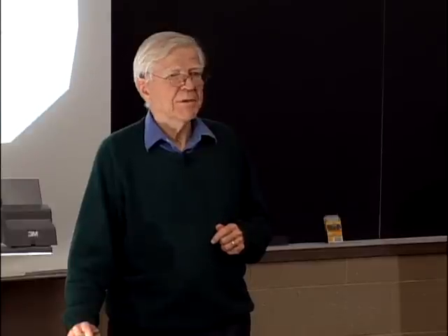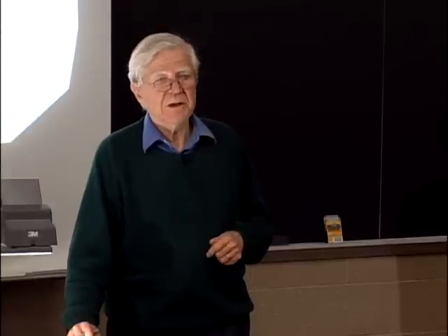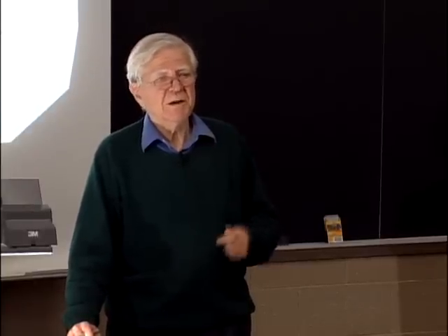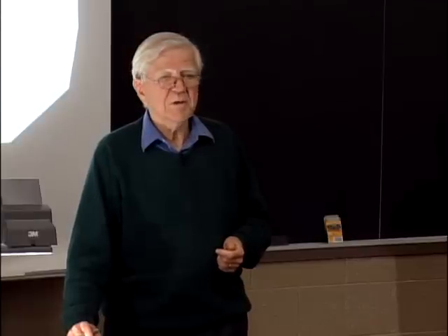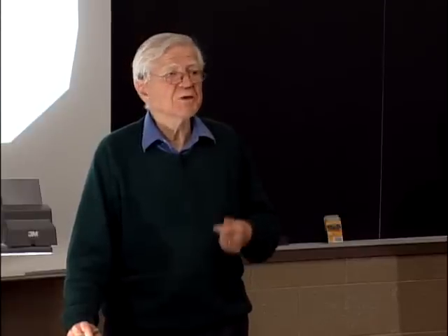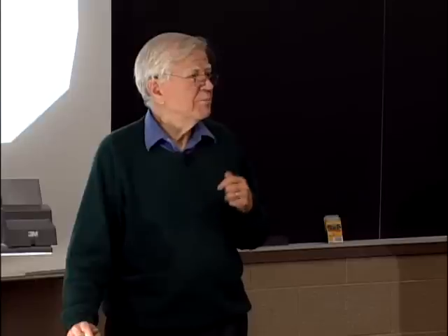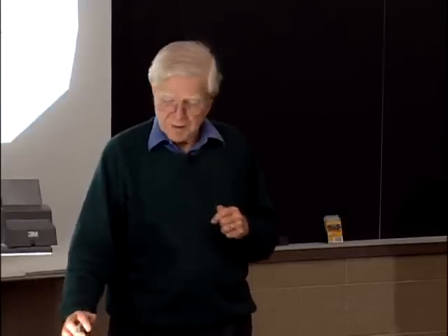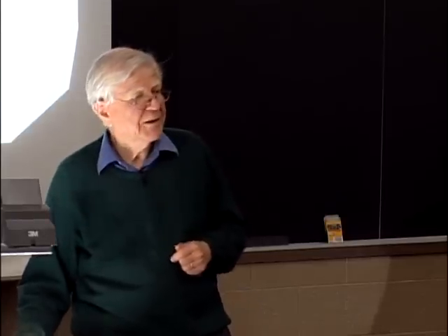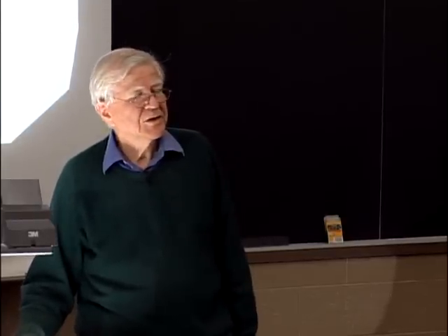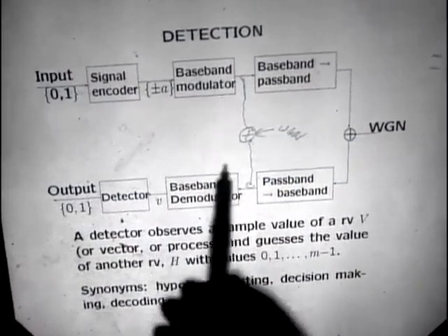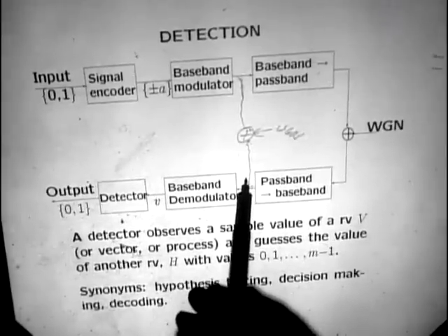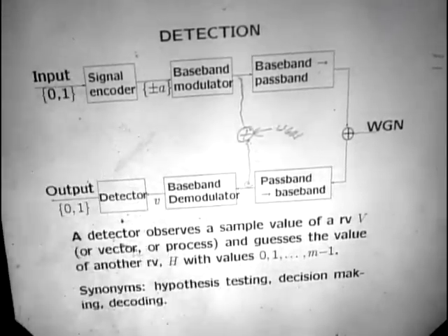Okay? So in fact, when we were looking at the Nyquist problem and worrying about inter-symbol interference, what we were doing was also doing the first part of an optimal MAP detector. And at this point, what comes out of here is a single number V, which is now the inner product of this waveform at this point with the waveform A that we sent.